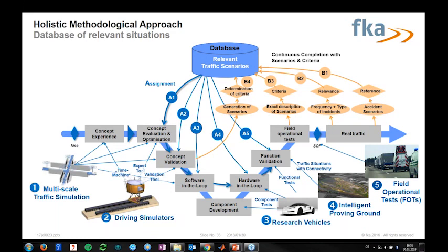So I see there is another question about the ASIL level. This is a quite difficult question, because of course it depends on the exact system we talk about, whether a level 1 system or a level 3, level 4 system. What was done in Convoy was not ASIL because it was earlier. I guess it was, I have to look into it, SIL 2.